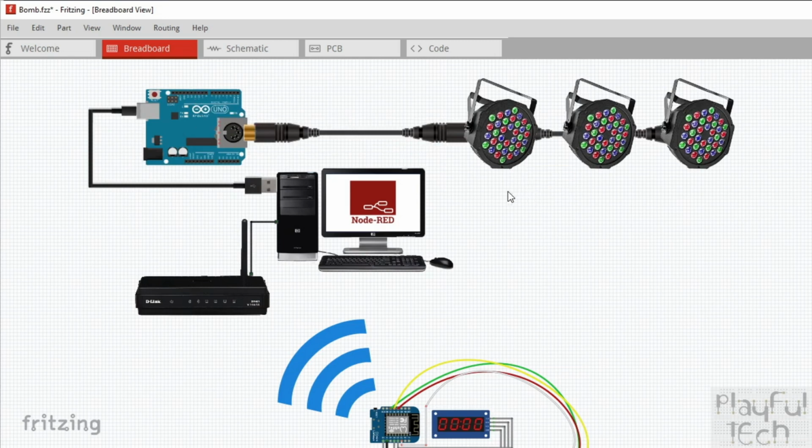But if you wanted to control them separately, to have them follow different patterns like a chase sequence, or to respond to different events because they're positioned in different physical parts of the room, that's easy to do as well. You simply provide an offset as to which channel set they're all listening to. So these lights always need 4 channels.